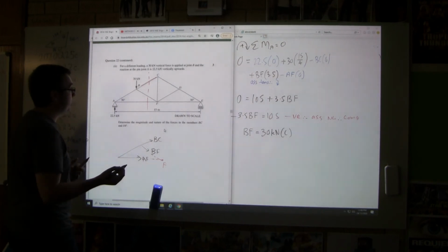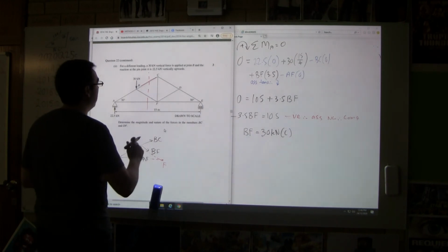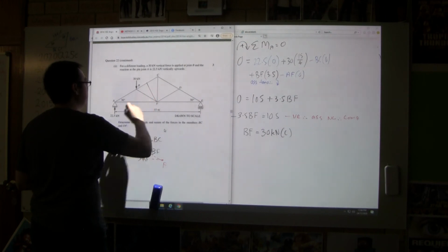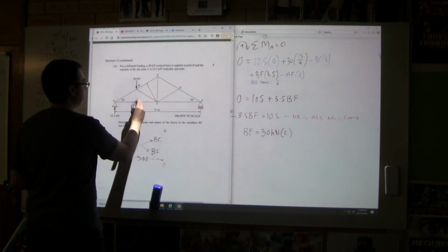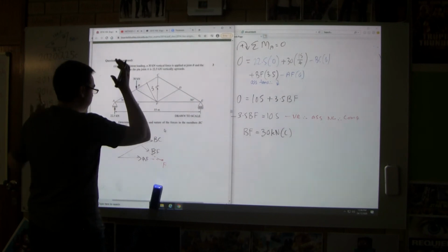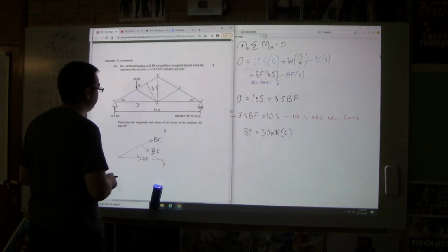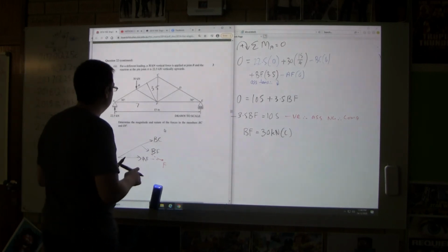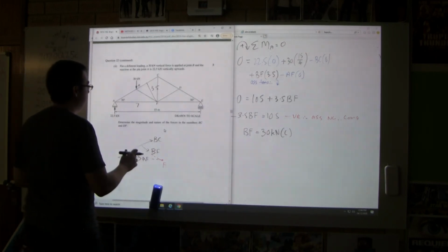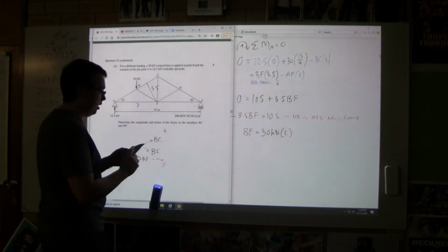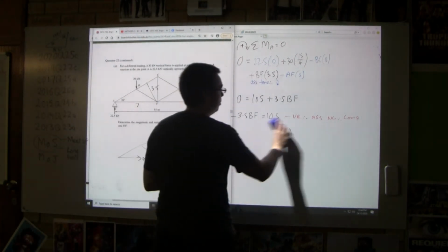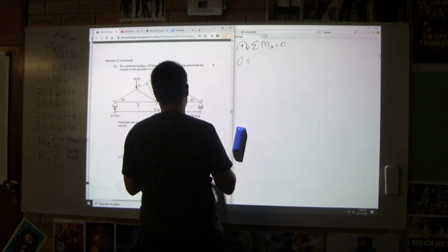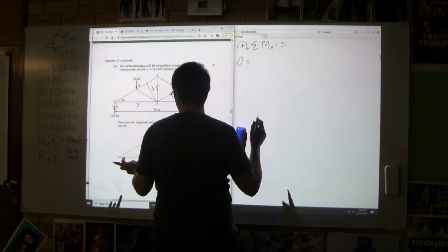Okay, this actually is probably easier than before. Our perpendicular distance that we found, I'm just going to draw this up here. If we know this is 7 and that's 30 degrees, that's going to be 3.5, even easier than last time. Just that ratio of big side to little side is 2 to 1. Okay, so what we've got now, if we have our perpendicular distance, let's go back to it. I'm just going to write this out. I'm not going to worry about writing all the unnecessary stuff here. I'm just going to say we really only have two forces.